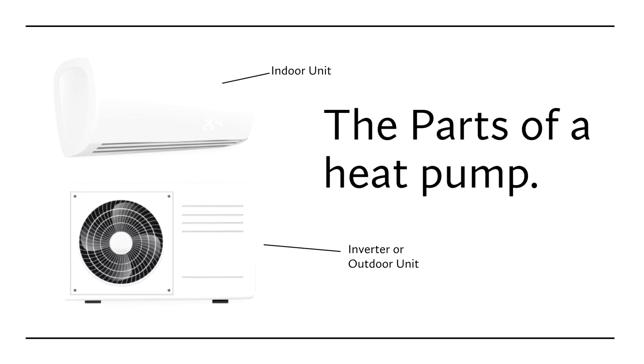So the inverter provides us the ability to take AC current at 60 hertz, and play around with the frequency that we're moving the pump or the compressor to move the refrigerant. So if we turn it into a digital signal, then we can do simulated AC with DC pulses to drive the compressor.